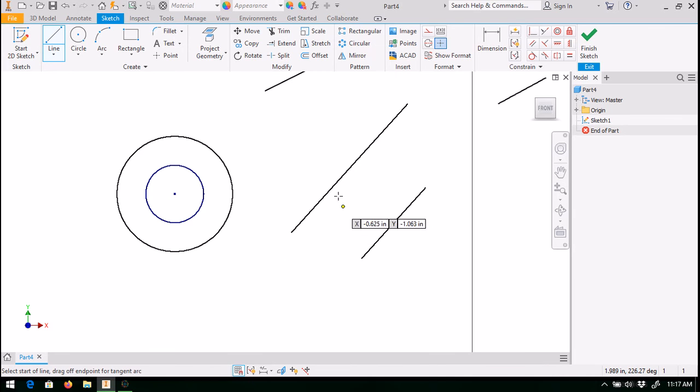So I guess you could say the inverse constraint relationship now would be looking at two line segments not being parallel, but I want them to be perpendicular. So if I take two segments, and let's have these segments touch, you can clearly see that if I were to measure the angle between them, it's about 65.8 degrees. I want that to be 90 degrees. I click on my perpendicularity constraint and click on the two segments, and you can see I have a nice